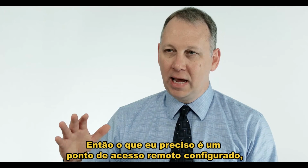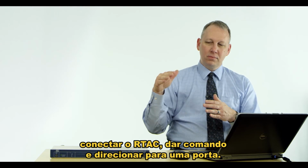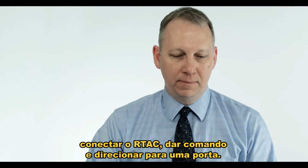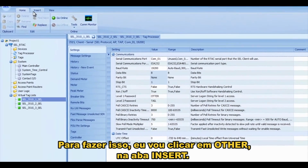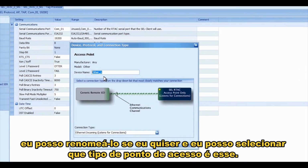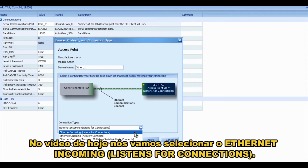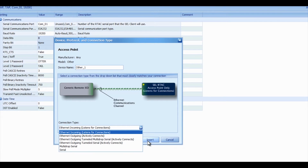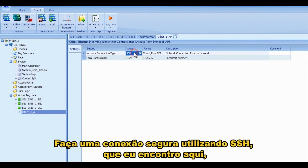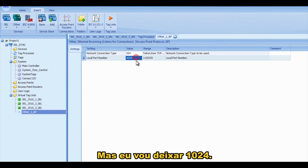So what I need is a remote access point configured so that I can, from a remote location, connect to the RTAC and then give a port command and tunnel to a port. To do that, I'm going to click on Other from the Insert ribbon, click on Access Point, and I can rename it if I want, and I can select what type of access point it is. Today's video we're going to do Ethernet incoming listens for connections. So we're going to connect to the RTAC via Ethernet. Make a secure connection using SSH, which I've got here, and the local port number you can change, but I'm going to leave it at 1024.